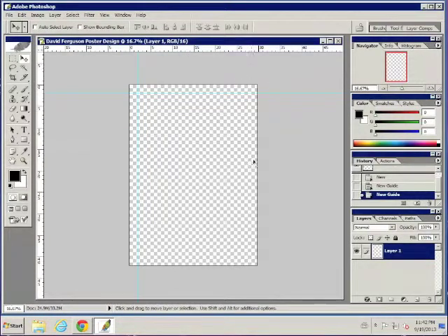Now to get the lines on the right and the bottom area, we're going to have to subtract obviously the width of the canvas. Now the width of the canvas is almost 30 centimeters, 29.5. So we're going to bring that back by 2 centimeters to 27.5. So I'm going to drag again from over here, and I'm going to pull that to 27.5. Now you don't have to be exact, that will be good enough. And then we're going to move to the top, drag down, and we're going to bring it to 40 because our canvas is 42 centimeters. And there we go. We have now our borders set.